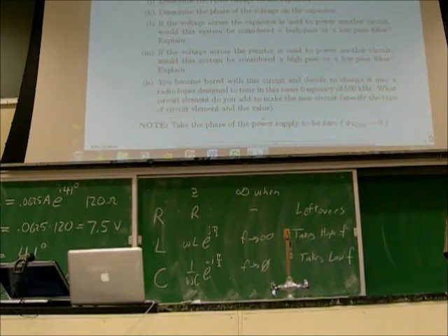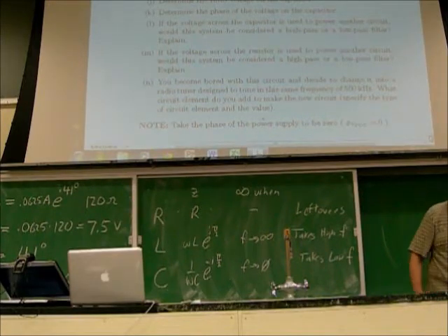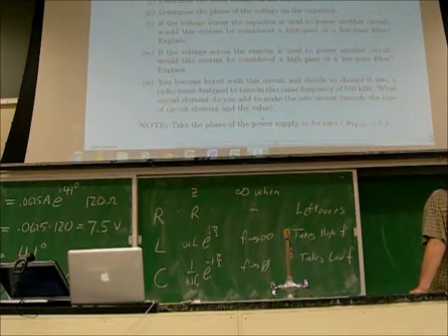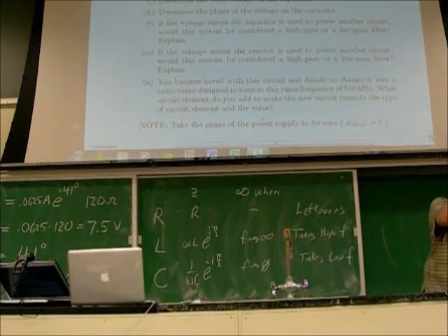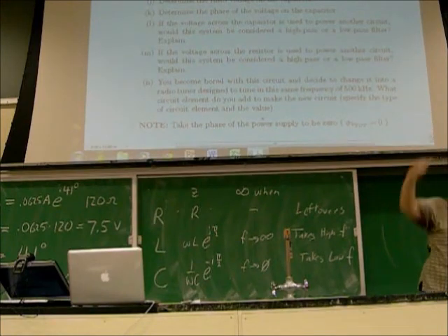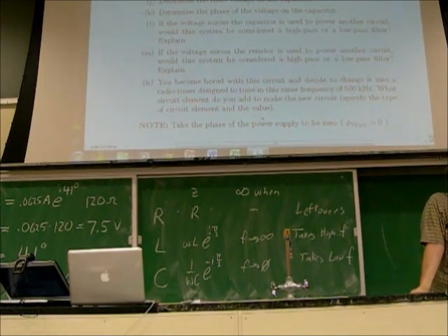And then in another application, I had a student who bought a preamplifier commercially, and he was going to send it into a circuit to amplify it, and he found, oh no, the worst thing possible. The little blips were there, but they were riding as little millivolt fluctuations on something that was up at 12 volts. What is he going to do? How can he amplify that? Because it'll amplify the 12 volts.